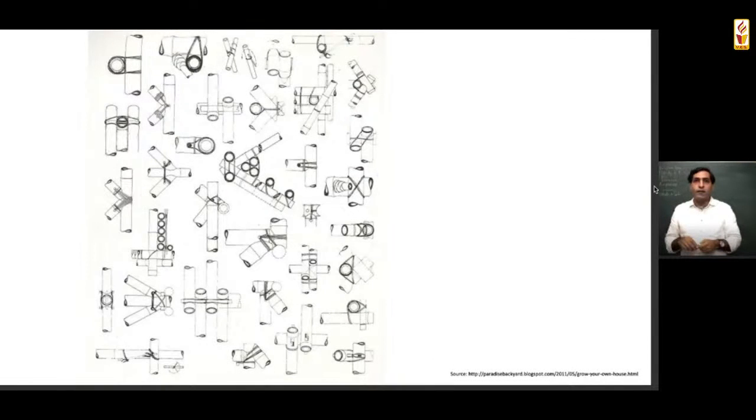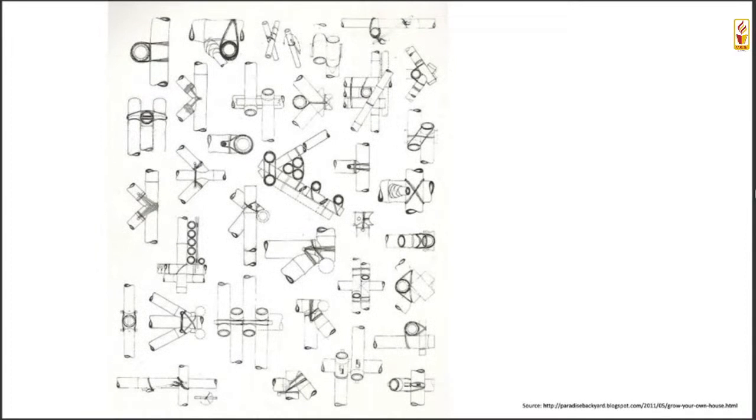You will find in textbooks, these are the standard ways in which construction happens. All of these are lashing joints. Many of them will work, many of them will not work, depending on whether you are using bamboo in case of furniture, or in construction, whether you're using it in a ground floor structure, or a G+2 structure.